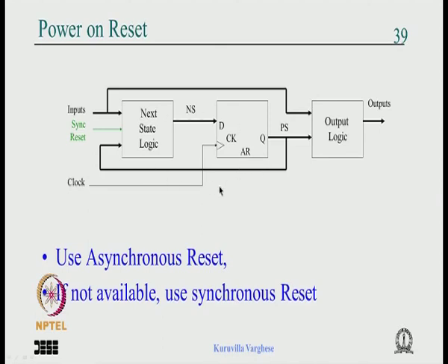This is a sequential circuit, but you have a data path as a pipeline, it is all the same. You have some registers, some flip flops, whose output goes through a combination logic and goes to some other flip flop. In this case, if you have Q1 and Q0, Q1 output may go through some circuit, go to D1 or D0 and so on, okay.